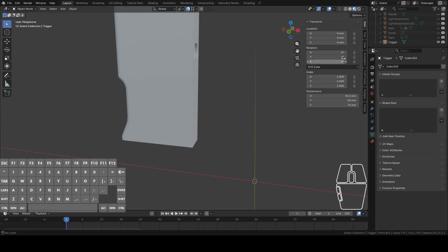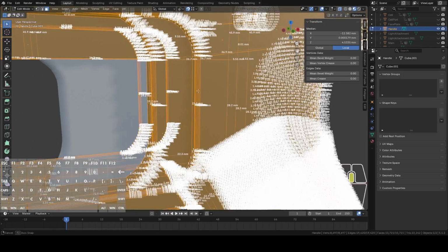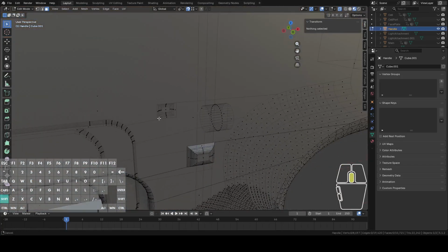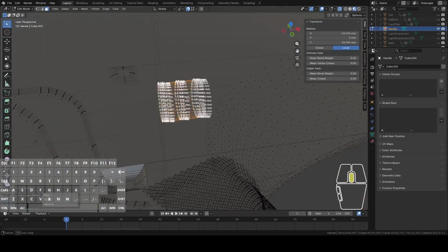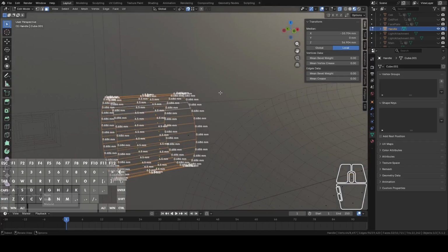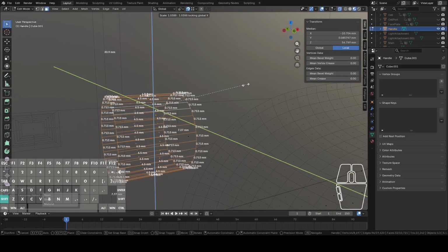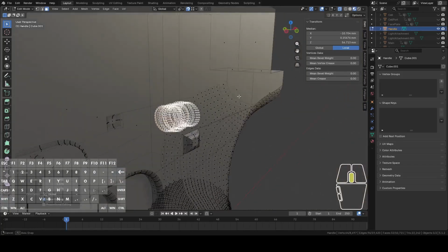And knowing that, I think the spring hole for the handle could also use that increase, because I was having a lot of trouble getting the spring in place just due to how deep in this is, how awkward the place. So widening that up shouldn't detrimentally affect it in any way. It'll just make it a little easier to slide in. So let's put this one at a 0.5 millimeter increase.